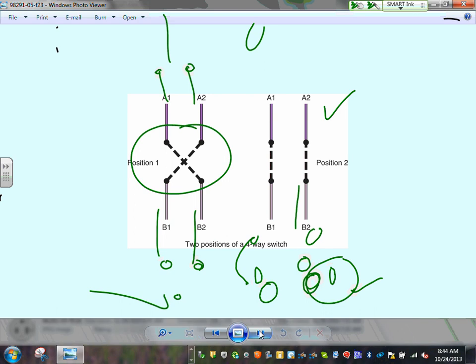switching. A 3-way switch and 4-way switch in a commercial building is not commonly used, guys. Unlike residential, you don't want to do it. Why? The energy code will force you. Did you guys hear me? The energy code will force you to use occupancy sensors and what's not.